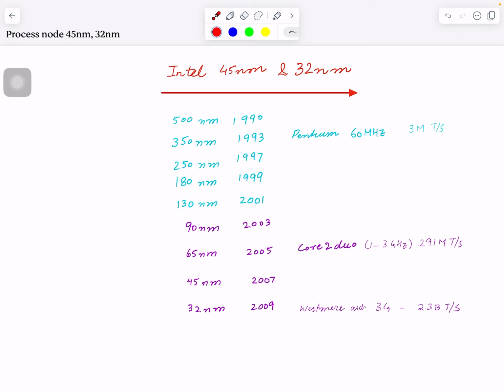That means area goes down by 0.5. And why this number, I explained in the very first video of transistor scaling. And the density doubles. The area gets half, the number of transistors gets double, density gets double. And then the performance: delay decreases by 30%, frequency increases by 50%. So those are some of the things, but it was with a natural kind of gate length change, and then adjusting everything around that.